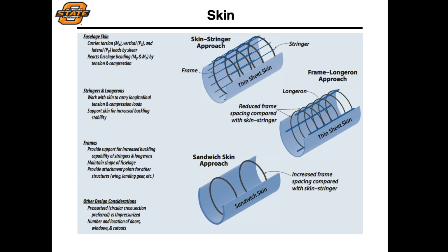So in this case, you can think about that fuselage as a pressure vessel, and then you can use the same pressure vessel equations that you're already familiar with to go through the process of designing the load carrying requirements and looking at the hoop and axial stresses acting on that pressure vessel.